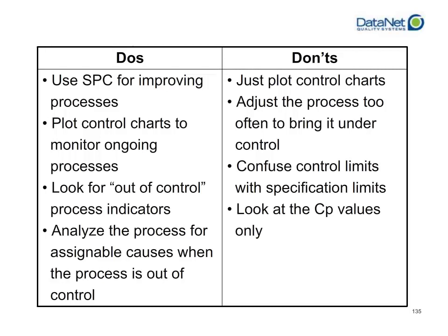Do not just look at a CP value when you're doing a capability analysis. That only tells you if you're theoretically capable of producing within control. It doesn't necessarily tell you that you're producing anything within spec. You need to run CP and CPK, which is really easy to do when you're using a real-time software package like WinSPC, as opposed to doing things by hand.